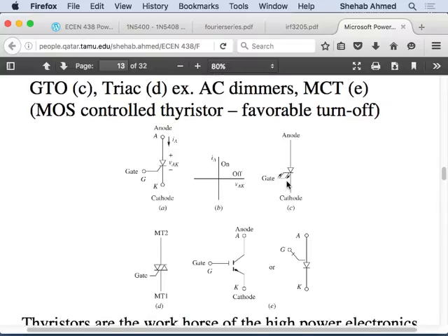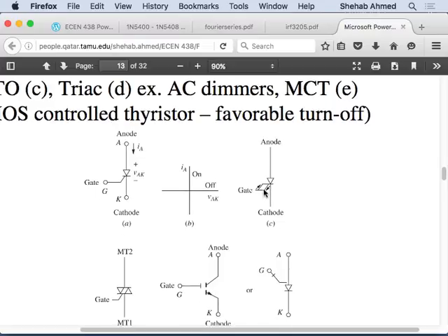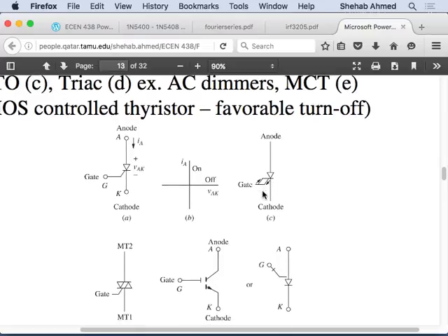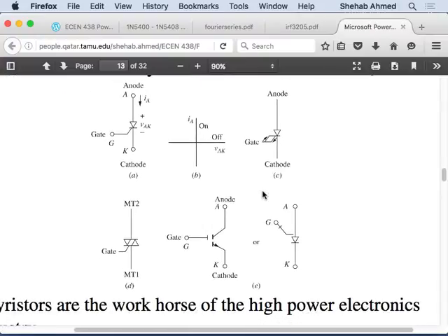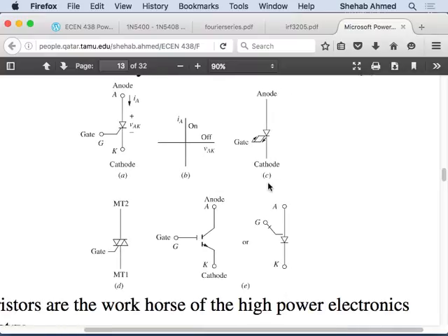And that's what you see here, like a bidirectional sort of thing, bidirectional arrows on the gate. So this is a thyristor that you can actually turn off. Then people came up with a different family of thyristors that has a gate that looks like a MOSFET. So instead of being current control, it's voltage control. So it was called the MCT type device.